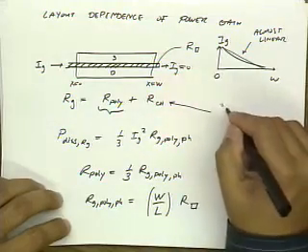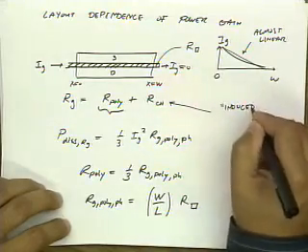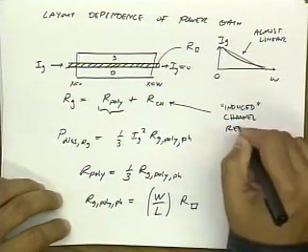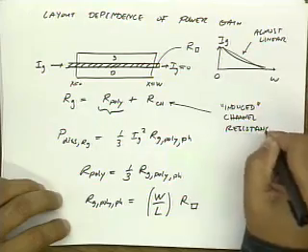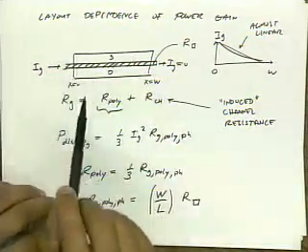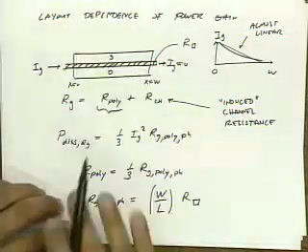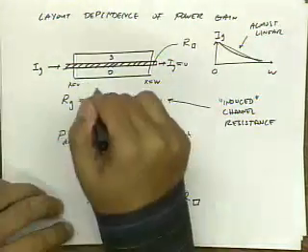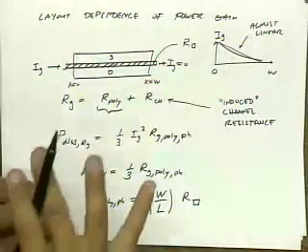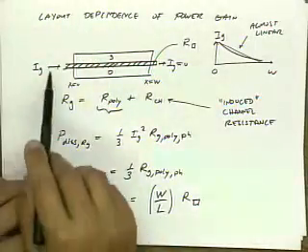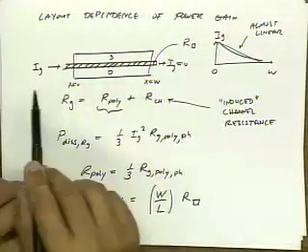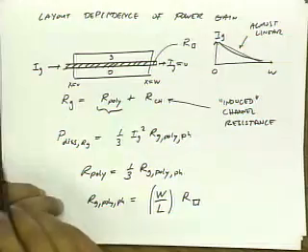This is the induced channel resistance, and it's proportional to the resistance of the actual device. It turns out that because the channel, the gate current flows into the channel and then it flows into the source and drain, because the channel is resistive, that actually contributes a resistive part into the input admittance. And to actually analyze that problem is quite complicated.